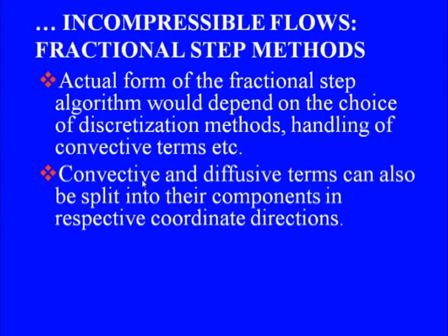Furthermore, we can split the convective and diffusive terms into their components in respective coordinate directions, and this can facilitate our computations, specifically when we use an implicit time integration scheme, wherein we have to solve a system of linear equations or linearized equations at each step.